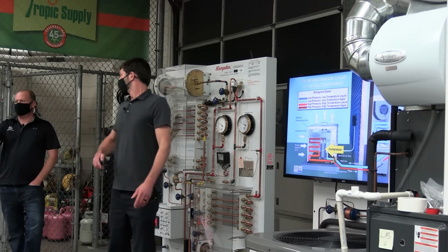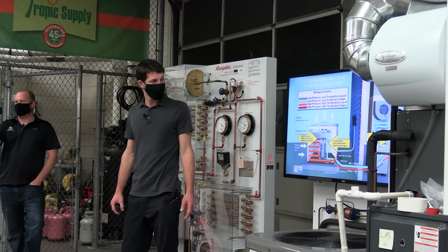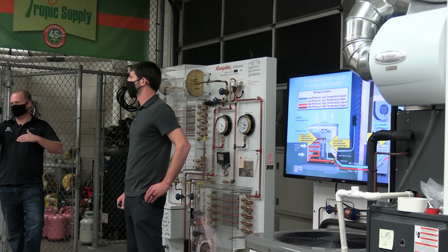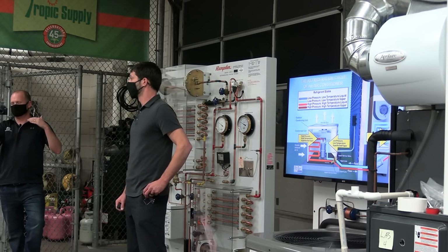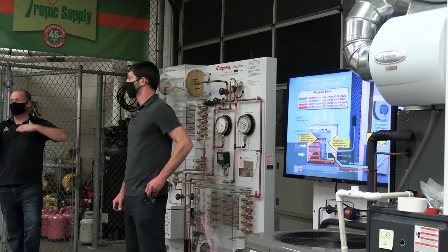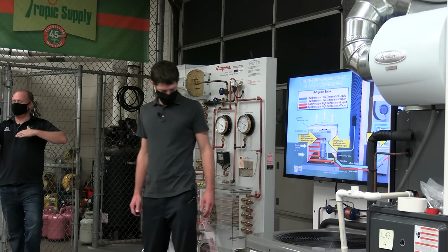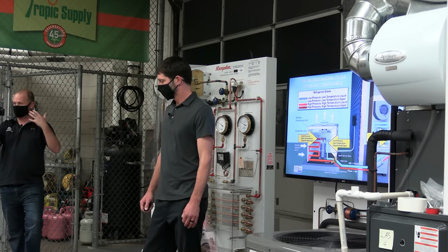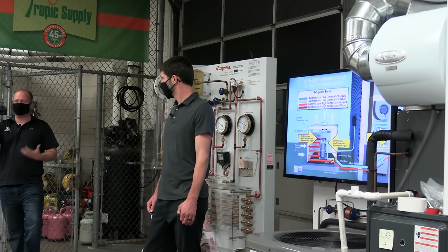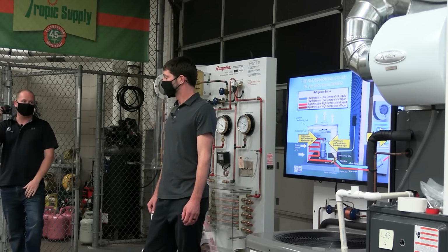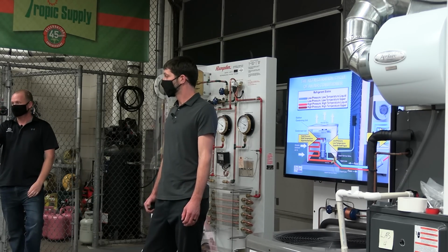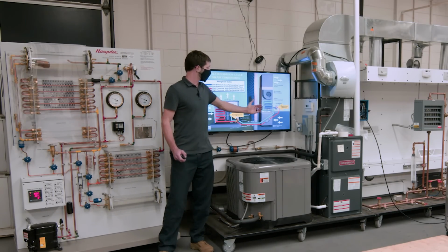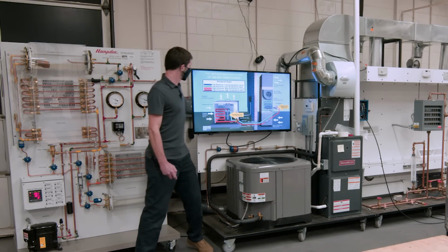Yeah, like we talked about the other day, you have to think about the temperature of the refrigerant in the evaporator. That's our saturated suction temperature, our evaporator temperature. But you also need to think about how full the evaporator is. And superheat tells us about the fullness of the evaporator in terms of the boiling refrigerant. Again, it's boiling refrigerant that effectively removes heat from the air that's passing over it. So I tend to call this a saturated state, but it's a phase change from liquid to vapor.